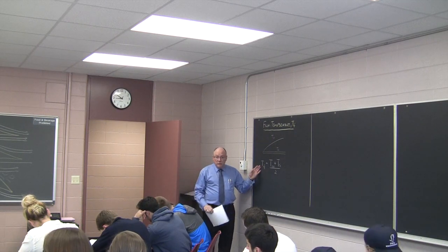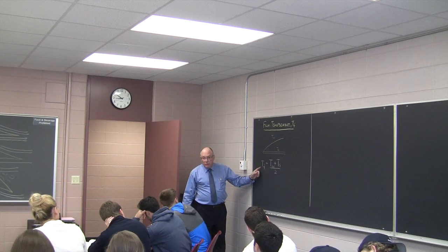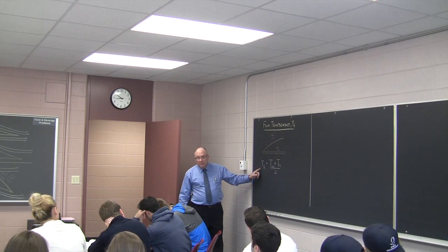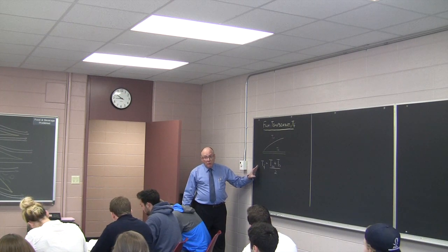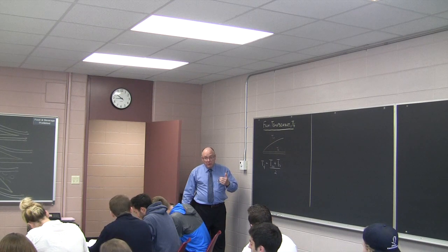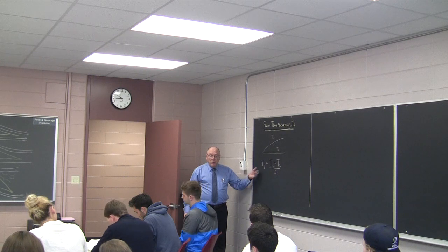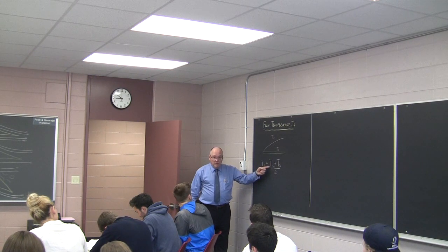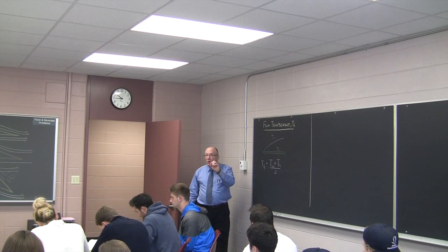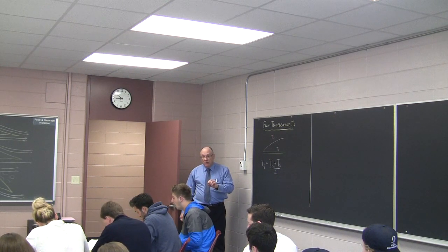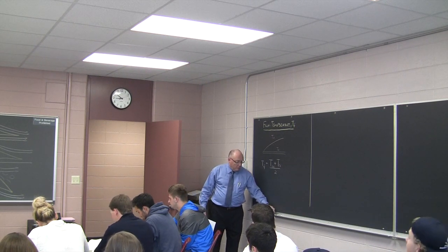And this is the value that you will use more often than not for most correlations to calculate your fluid properties. Okay? These empirical correlations which we use are based on different techniques, either using this, sometimes using this, sometimes using this, as I've been describing. So you need to look at what's required in the correlations before you use them and ensure that you comply. That's the film temperature. Any questions?